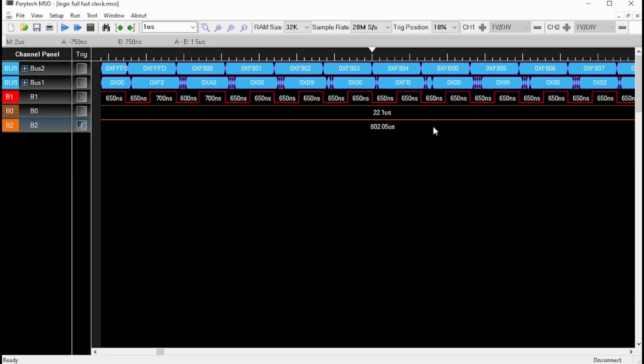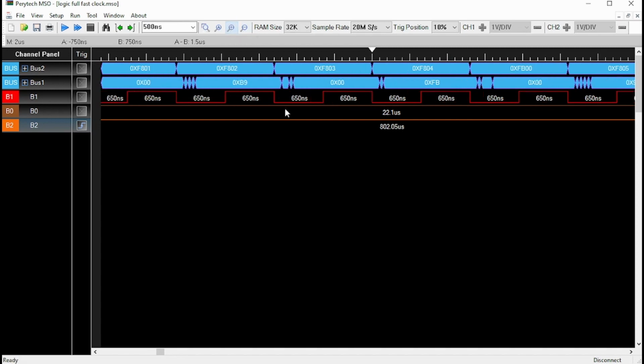It's pretty stable. But one thing you would notice is if we look at the data lines, we see these items here which we've not seen before. And when I first did this, I thought there might be something wrong with the circuit or something wrong with the logic analyzer. But after questioning the community on Facebook, I'm learning that actually this is a typical way that a circuit will operate when you're interfacing with RAM chips or ROM chips or any memory, that you have to wait a certain period before you get sensible data on the data bus.